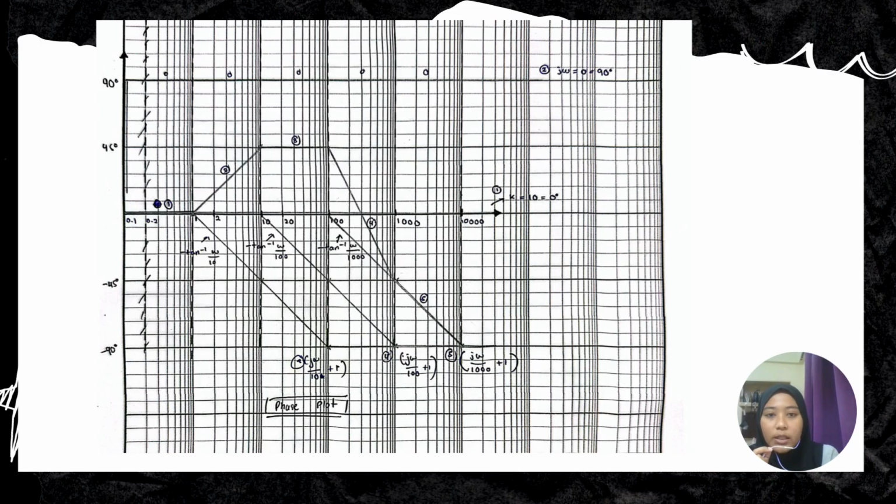As the frequency increases and approaches the corner frequency, the phase begins to decrease gradually. Each pole in the transfer function contributes a -90 degree phase shift, and this change occurs smoothly over approximately 2 decades, from 1 decade before to 1 decade after the corner frequency. Next, I will pass the next explanation about this plot to Wardah.